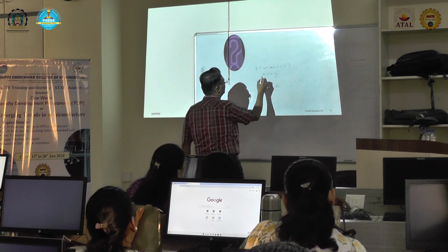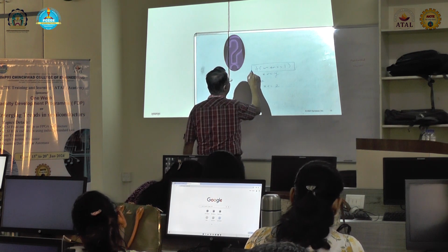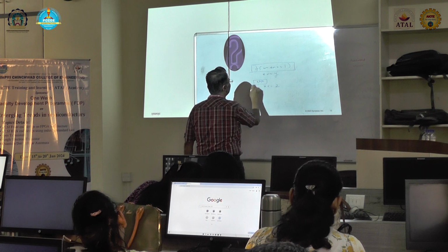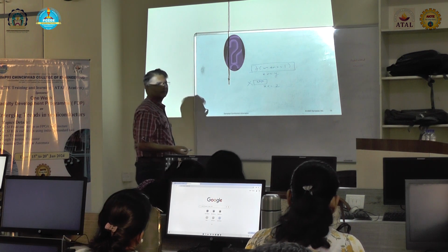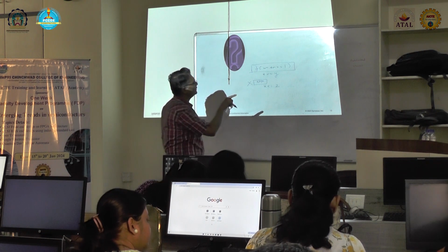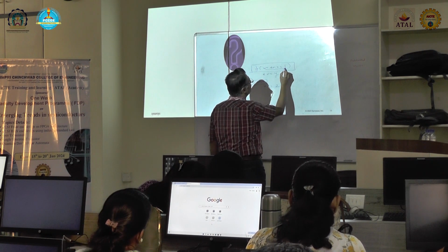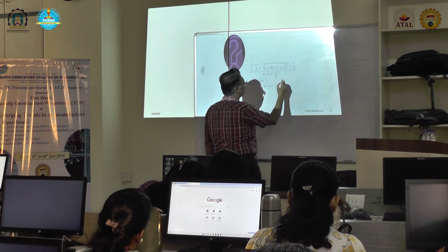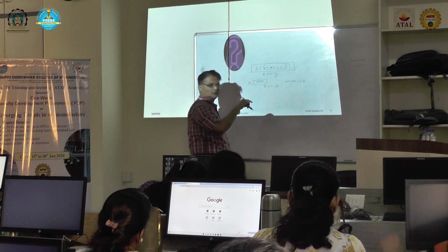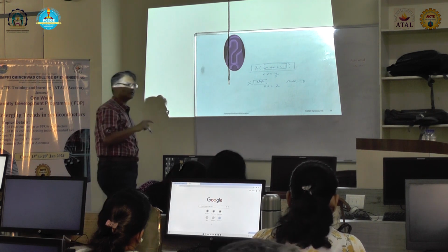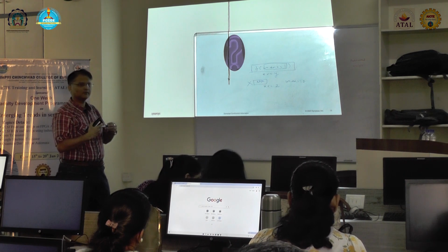Now the code coverage will tell you that this part is covered, but this is not covered in simulation. When you have simulated, it means you have only tested the condition when this signal is 1. You have not tested for write enable equal to 0. So your test needs to be enhanced to cover this condition. Synopsys does give us code coverage.